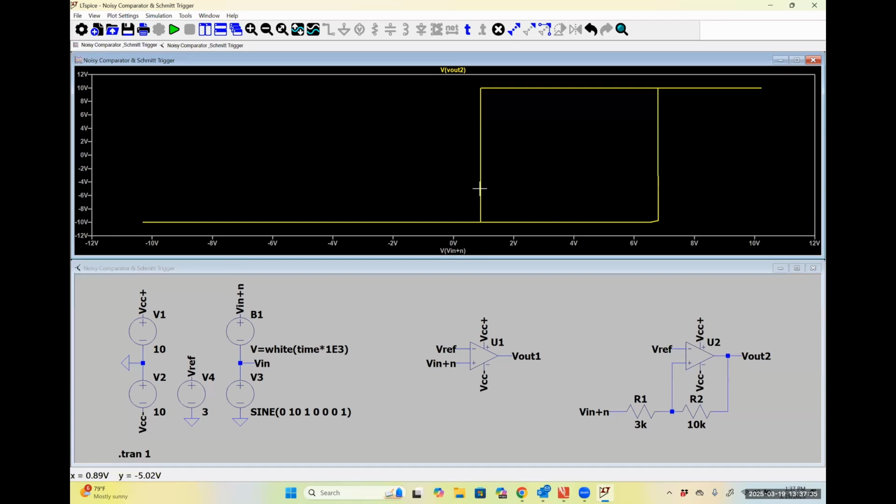For what it's worth, I want to show you guys essentially how to read this graph, because this is exhibiting what we would commonly call hysteresis in our signal. So essentially what we've got is our input signal is starting at negative 10 volts, and then it's gradually increasing, okay? Keeping on going until we hit our upper trigger limit. Then it's swinging high.